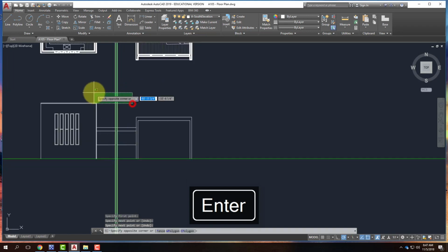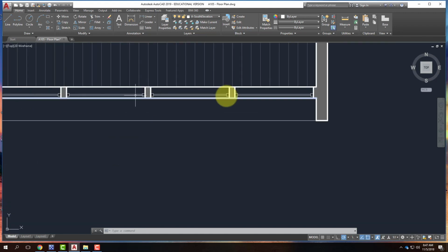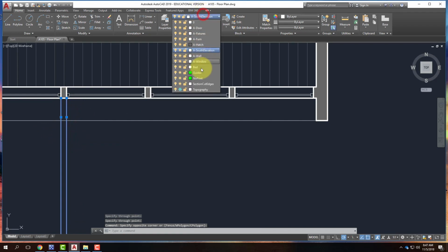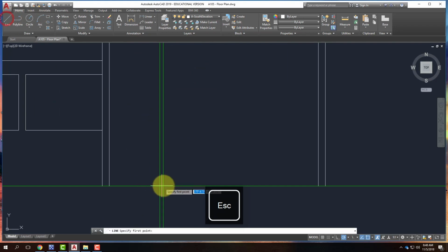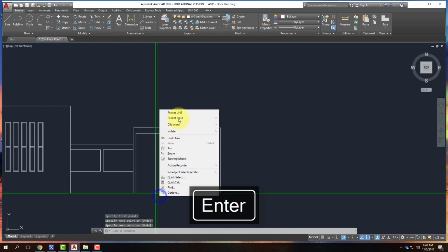And so I could continue to develop those windows. Let me delete these rays so you can start to see them. I could continue to develop those windows a little bit further. I could add the frames, etc. Likewise, this wall here is a curtain wall with lots of tall windows and little divisions. So same thing. I could use a ray there and there. And I could come down and draw the style in between the curtain wall windows.